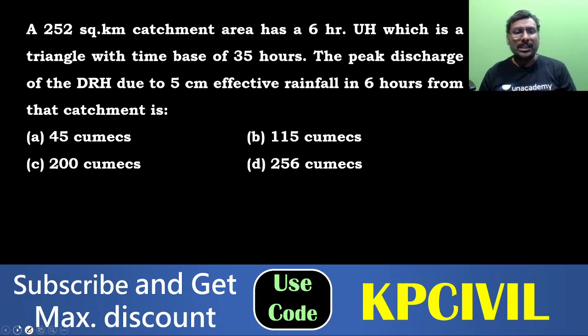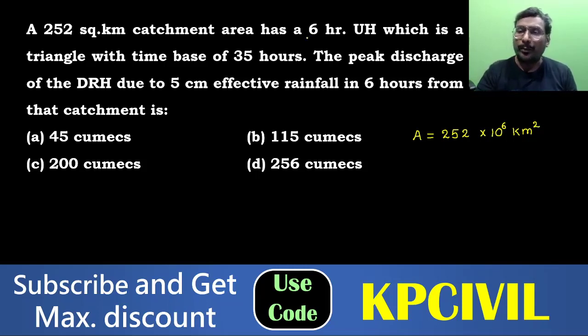A 252 square kilometer catchment area, that is 252 into 10 power 6, has a 6-hour unit hydrograph. Very important, remember. It is a triangle with a time base TB of 35 hours.